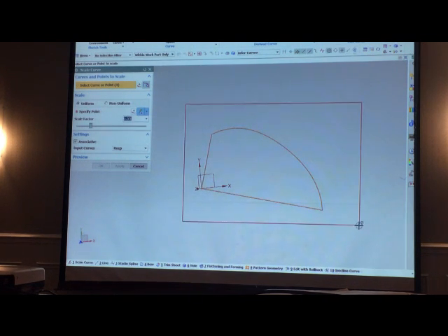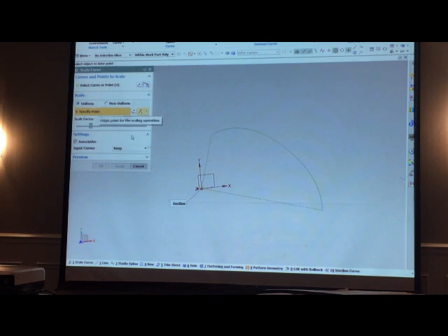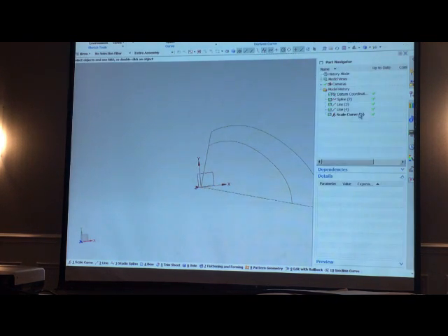So now I can pick the curves. I define a point. Let's take the origin point here. And, oops, I don't want the point. I want to define the point. There we go. And so now I can scale it using either a slider or an expression. Let's say 75%. So there's 75%. And I have the option of either keeping or getting rid of the input curves. And it is a fully parametric object. I can now come in here and edit it and say, gee, I want that to be 85%.